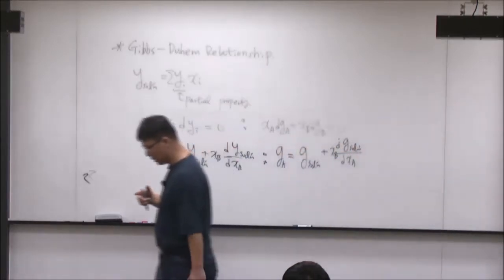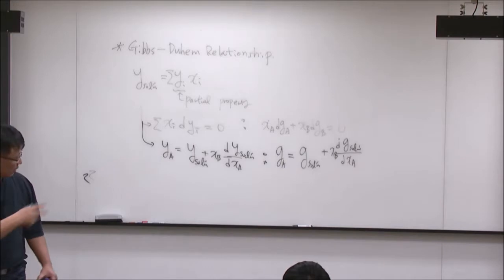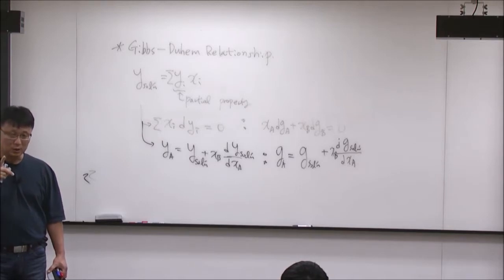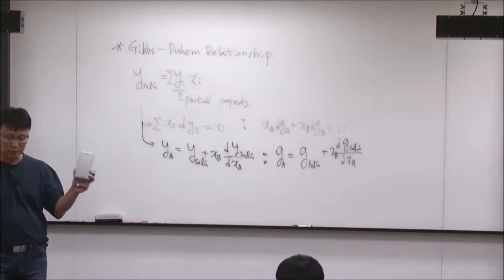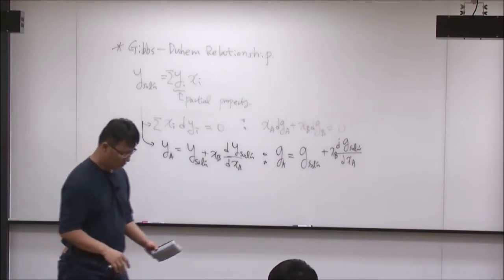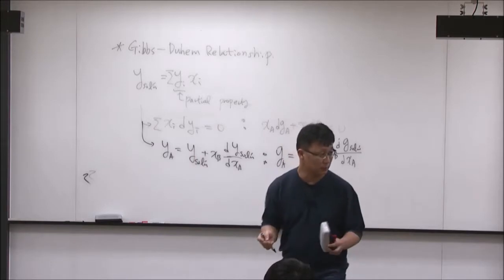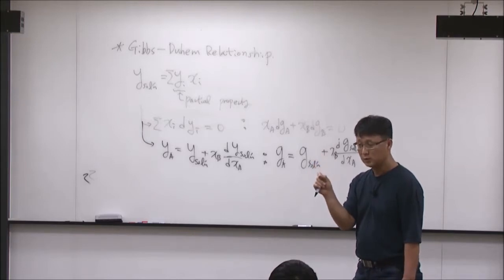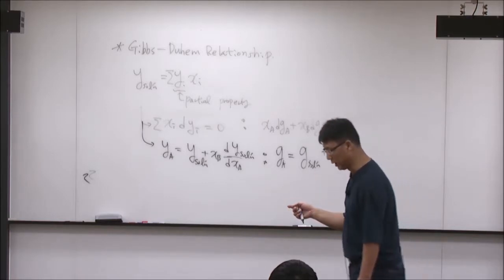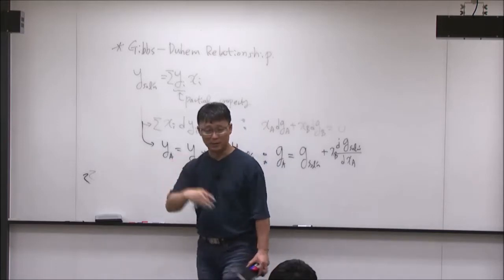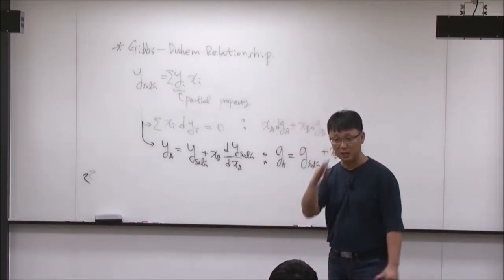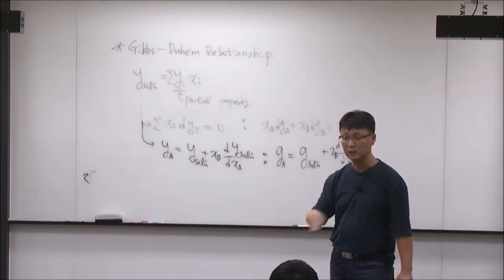When we are really using this kind of partial property or Gibbs-Duhem relationship, there are typically two cases, if we look at most thermodynamic assessments or thermodynamic measurements. People use the Gibbs-Duhem relationship mostly for two kinds of cases. One is when we are measuring the enthalpy of mixing of the solution. So let's assume we have liquid iron and liquid manganese forming a liquid solution. We mix these two together, and we try to find out the enthalpy of mixing of the binary liquid phase.